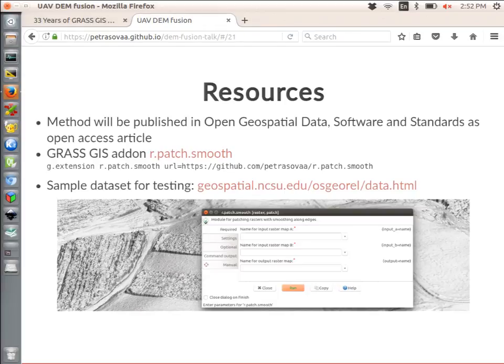Is adjusting the data so that you get a nice, smooth fit part of your process? It's not part of this. This assumes already that you were able to match it as best as possible. We didn't really have this problem because the LiDAR data are in really good shape, and for the UAS data sets, we had GCPs, which improved the UAS-based data sets a lot.